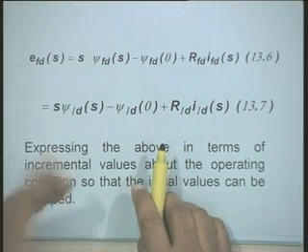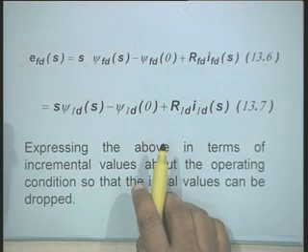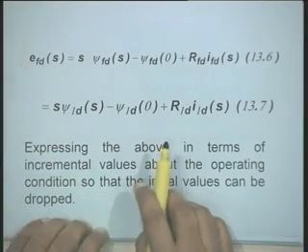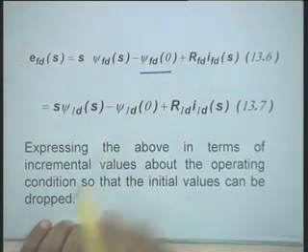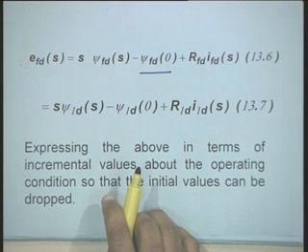That is, you take again the standard equation for the field circuit, because in the case of the field circuit we have the term d by dt of psi f d. When you take the Laplace transform of the derivative, the initial condition will appear here, because in the previous equations these were algebraic equations.